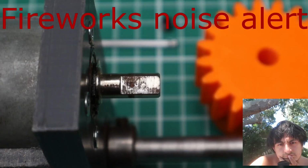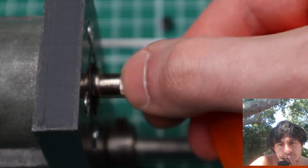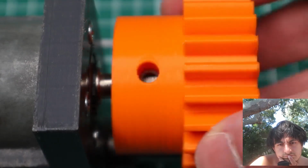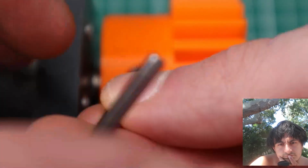I would now like to show you how you can put this gear on a shaft. So we take the gear, and we take care to align the hole of the set screw with the flat part of the D shaft. And with that alignment ensured, we push the gear over the shaft, and then we take an Allen wrench and a set screw, like this, and then we simply drive the set screw into the hole.